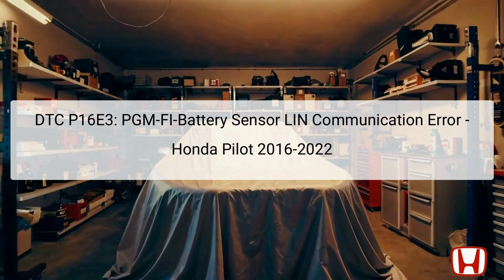Welcome to this diagnostic presentation on the DTC P16E3 error code, specifically related to the PGM-FI battery sensor LIN communication error for the Honda Pilot models from 2016 to 2022. This fault indicates a communication failure within the battery sensor's LIN, local interconnect network, communication line. This can disrupt vehicle operations, particularly functions dependent on battery status, like charging and power management.